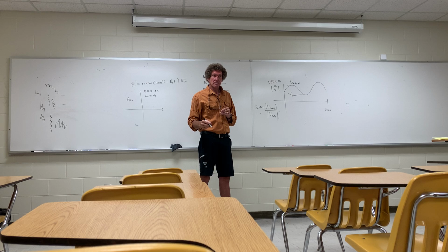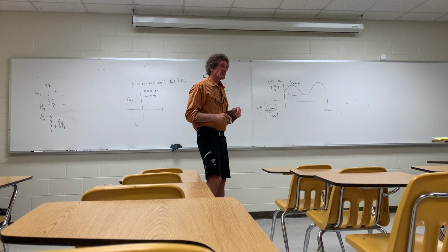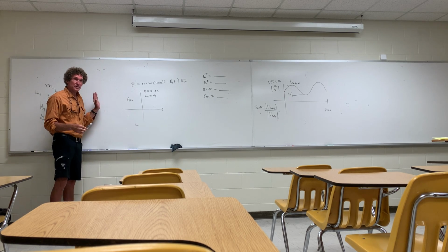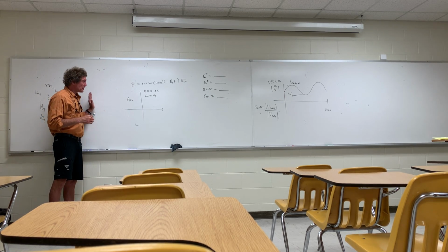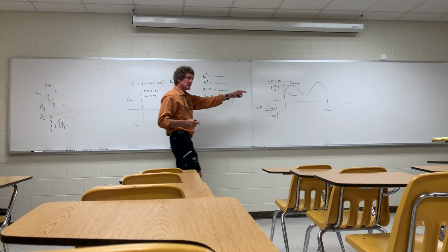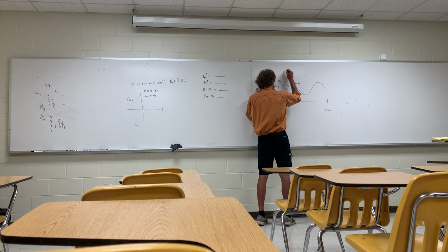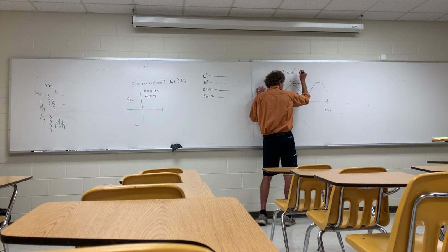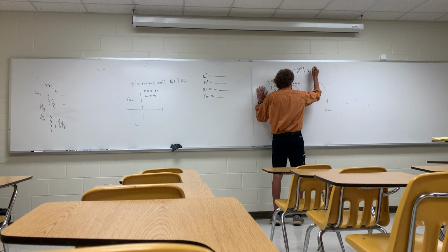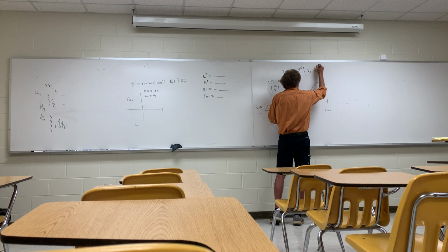Well, when we talk about electromagnetic propagation, we've got two media, and we want the standing wave ratio. Think of it this way. You've got a voltage coming incident. Remember back here, what is this going to be? The phasor V in general was V0 plus times e to the minus j beta z, plus V0 minus times e to the plus j beta z.